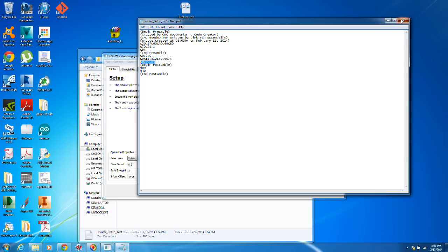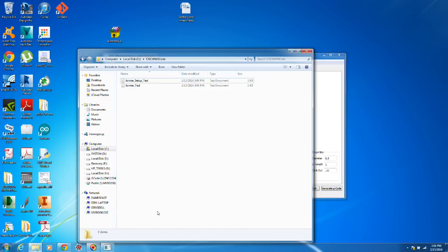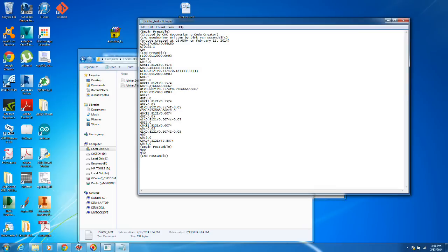All right. Then the other thing is actually the G-code that you would run, and of course here you go. In my machine, this is actually turning it on. So you have to have it in a safe location before you turn it on. That's another requirement, I should say. So it turns it on, and I've had issues with Mach at some points. It doesn't start the spindle, so I always put a pause statement for 5 seconds before it goes.